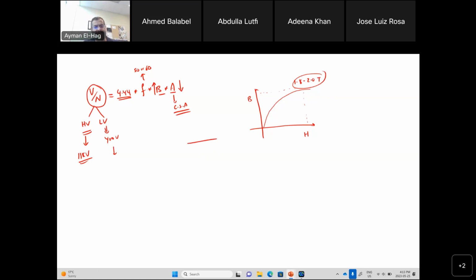So basically, if I have a transformer like this, this is your primary voltage, and here it is your secondary voltage, and this is open circuit. I do not connect anything here. So the current that we call the no-load current will be highly distorted, and that will affect the waveforms of the supplies. We don't want to have this at the testing transformer.